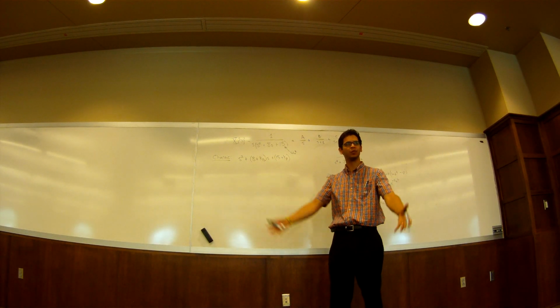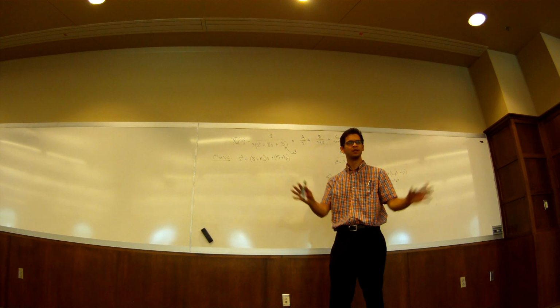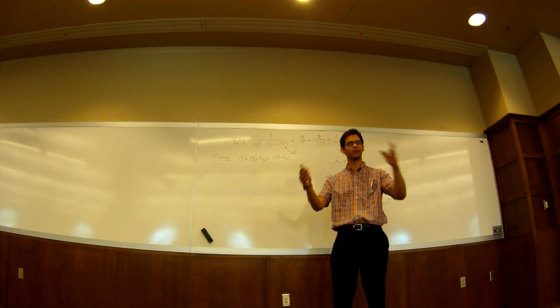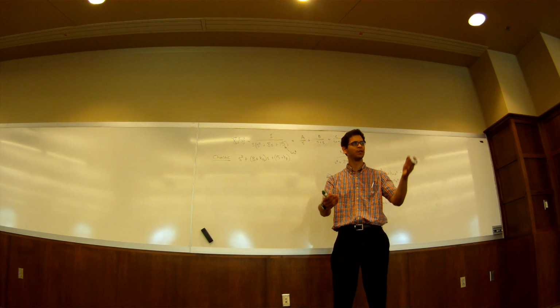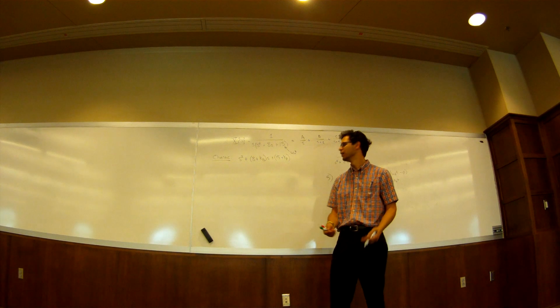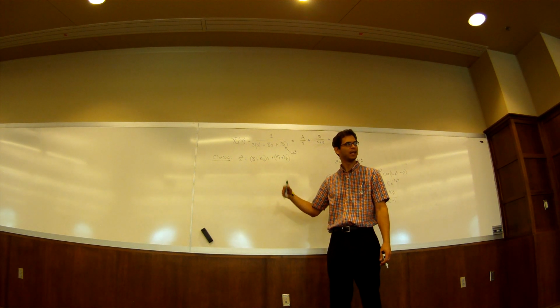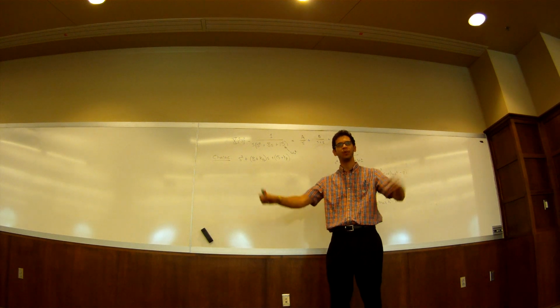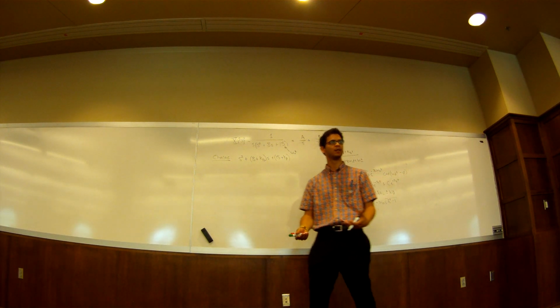What is a root locus? It's a plot on the imaginary and real axes. And what are you plotting? The roots, the pole positions, exactly. The poles are going to change as you change Kp and Kd, and it's going to move your poles around the real-imaginary plane, and you're going to make a plot of that.